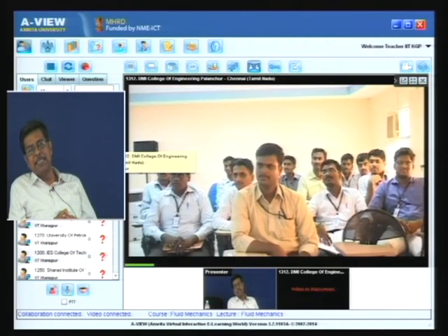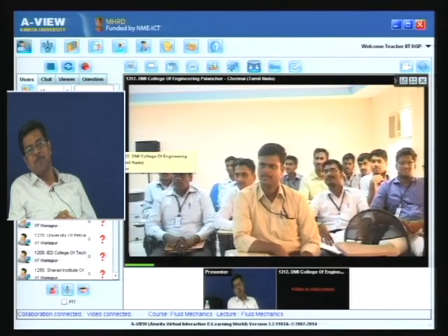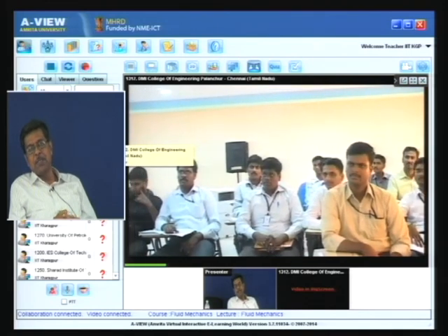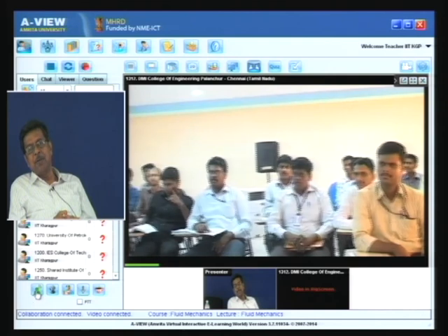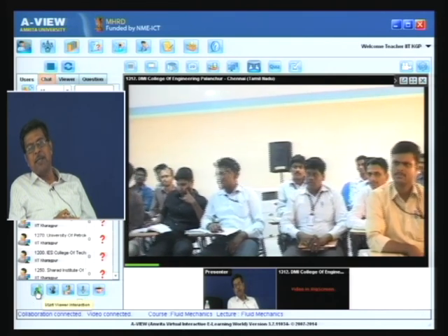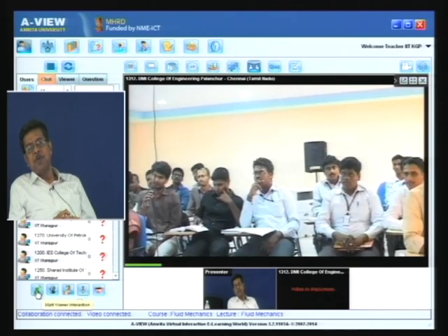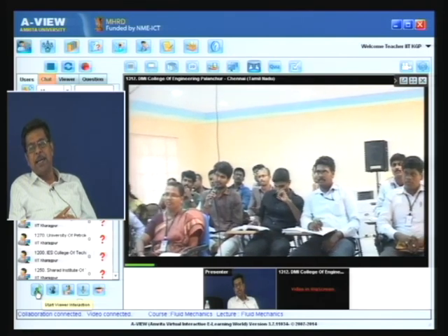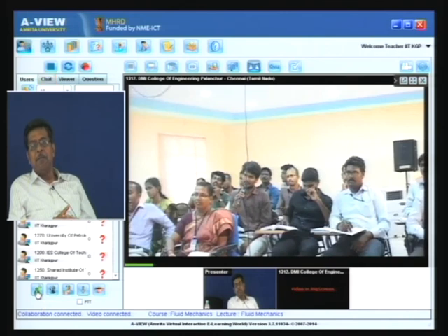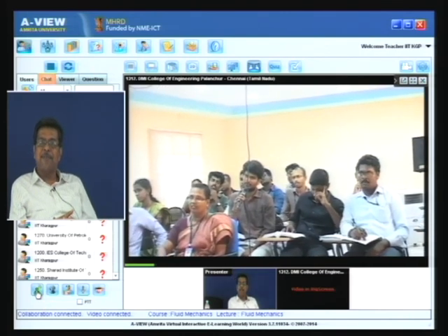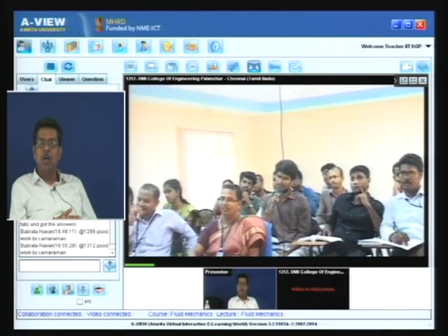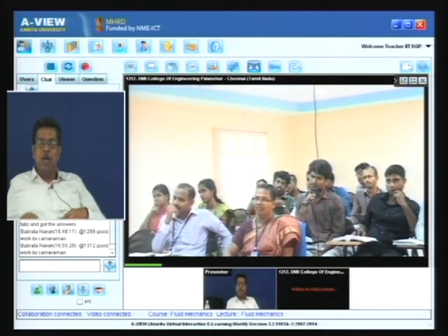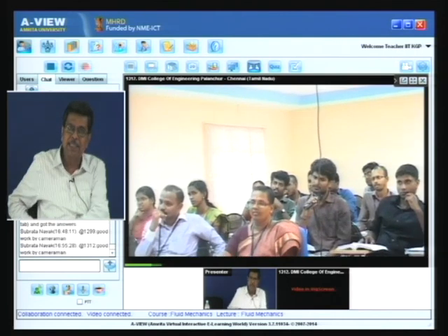If this is at steady state, the inflow mass and the outflow mass will be the same. It is exactly not the same, because in the outflow, along with air there will be fuel. Sometimes in our usual analysis we neglect it, because in a gas turbine engine or an aircraft engine, the mass flow rate of fuel is very less as compared to the air. The ratio of air to fuel mass is almost in the range of 60 to 100.